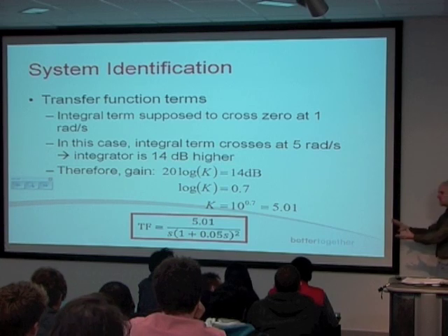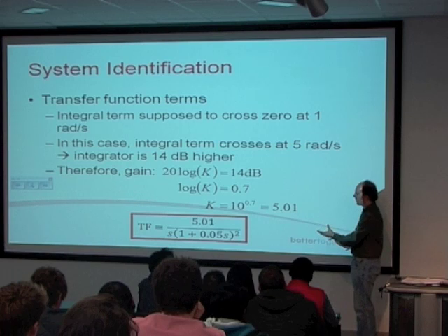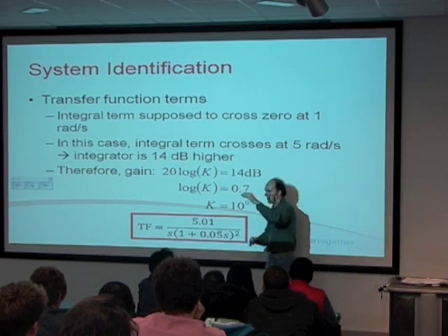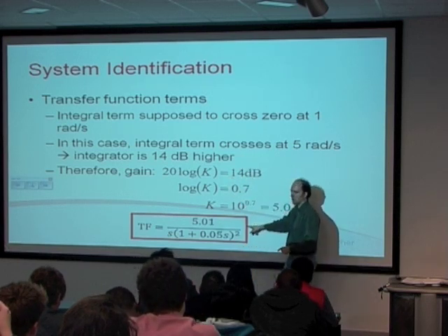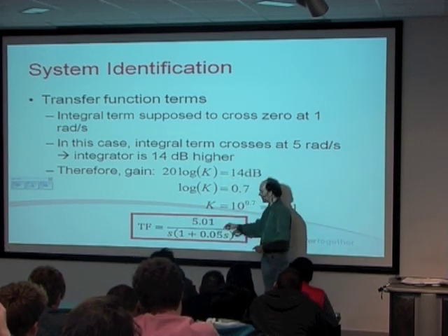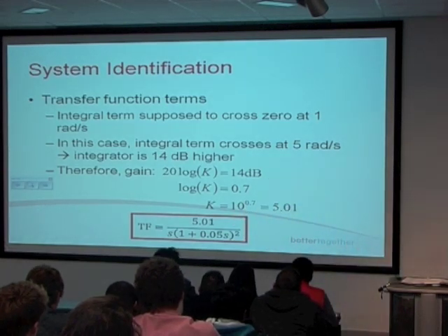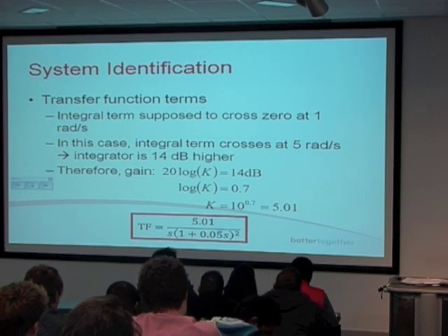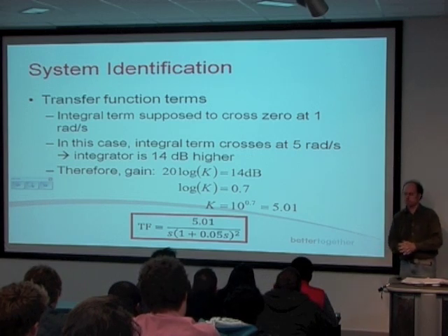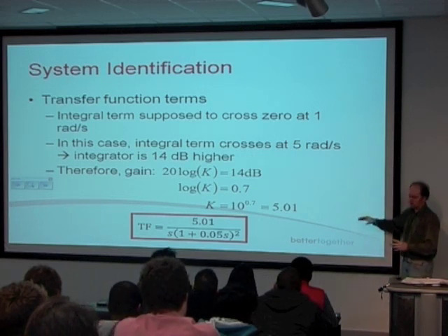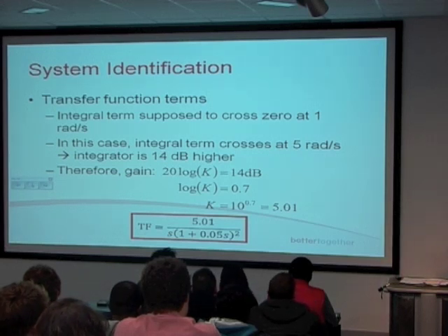What you do is you take your system, you generate a range of different frequencies, and you generate a table of data. You plot that data on a Bode plot. You then go through the steps we've done to generate the transfer function. You can then plug your transfer function into your block diagram, design the controller so that that block diagram behaves the way you want it to, and bam, you've got a controller for that system without having to know anything about the system beforehand. This is the advantage of this sort of method, and this is called system identification.